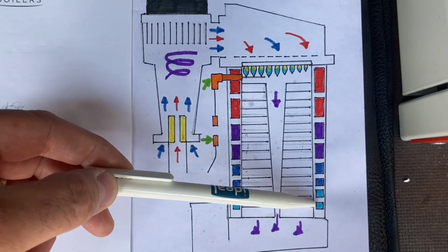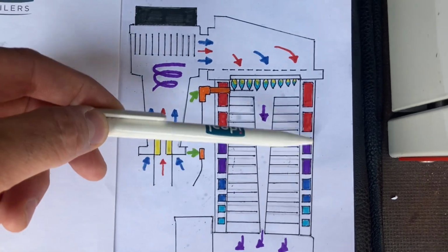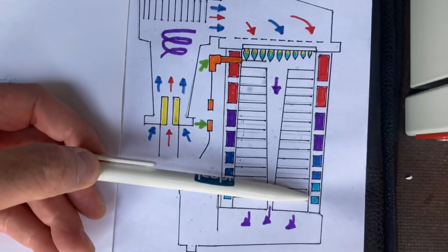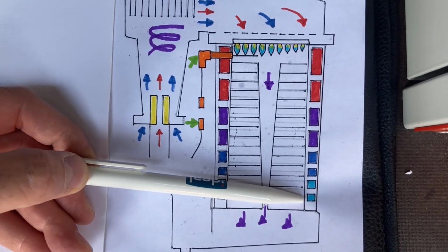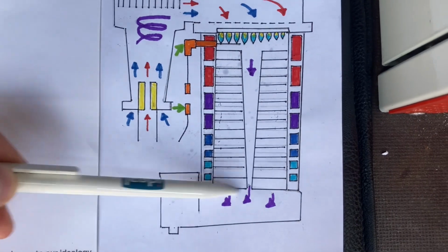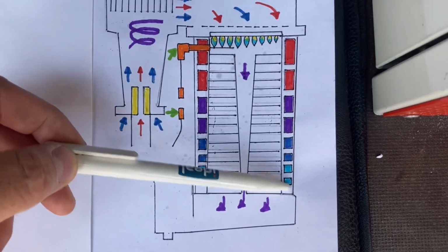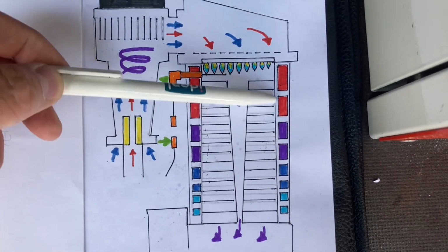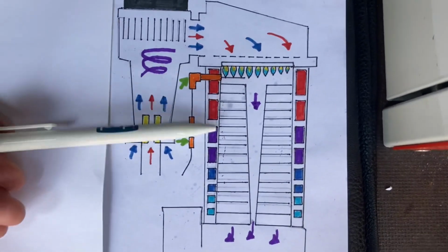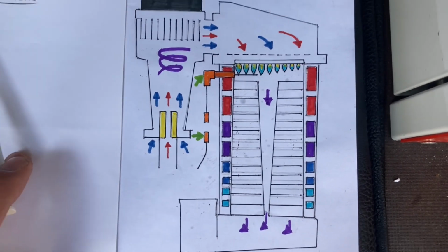I tried to depict cool water coming in at the bottom, and as it gets to the top, it gets hotter. I've even shown that the heat exchanger is split in two halves, so when the return comes in, it splits two ways, and the waterways are smaller at the bottom and larger at the top. They reconvene at the top and then come out the flow pipe. I've even gone to town on this picture, but